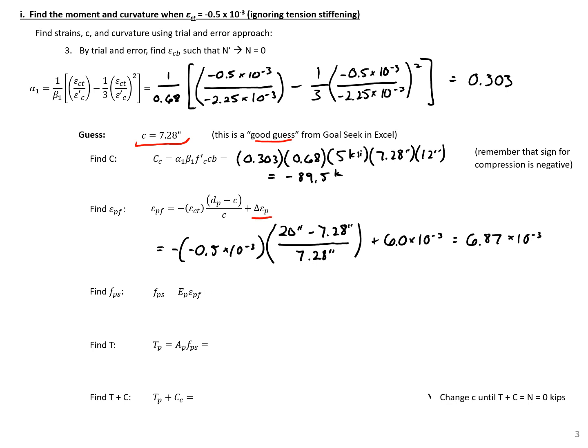The stress in our pre-stressing, we're going to assume that we have a linear elastic response. So we have our stiffness for our pre-stressing, 28,500, times the strain in the pre-stressing, 7.87 times 10 to the negative third. And this will give us a stress in the pre-stressing of 195.9 KSI.